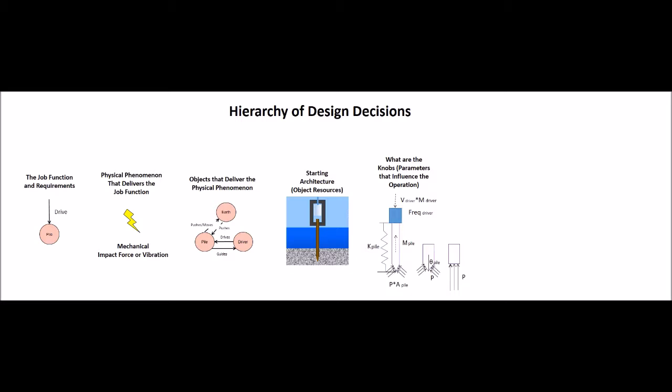Also, what is known as the spring rate or stiffness of the pile has a lot to do with the pile resonance, or the force that reaches the tip of the pile. The spring rate or stiffness is how much the pile compresses when a force is applied at the top. If the pile is very stiff, a lot more of the force reaches the tip of the pile. Next, the ground exerts a pressure at the tip of the pile.